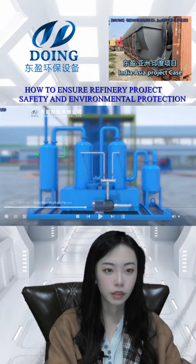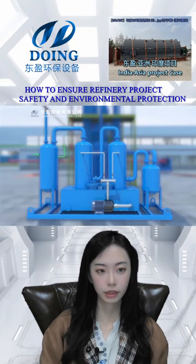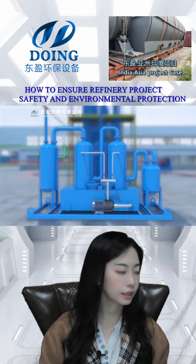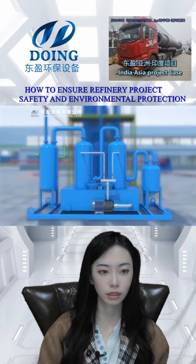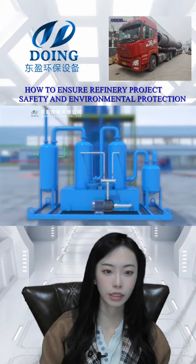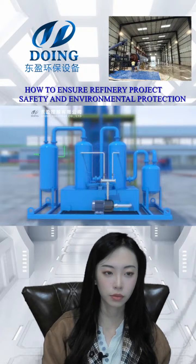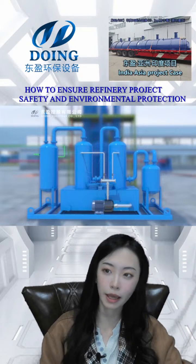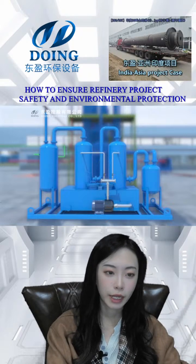And then this is where all the oil gas will be condensed, and the non-condensable gas from this condensing tower is called the tail gas. It will enter our standard safety device, the water seal, which can prevent the tail gas from flowing back. And then it will come to the environmental protection device.